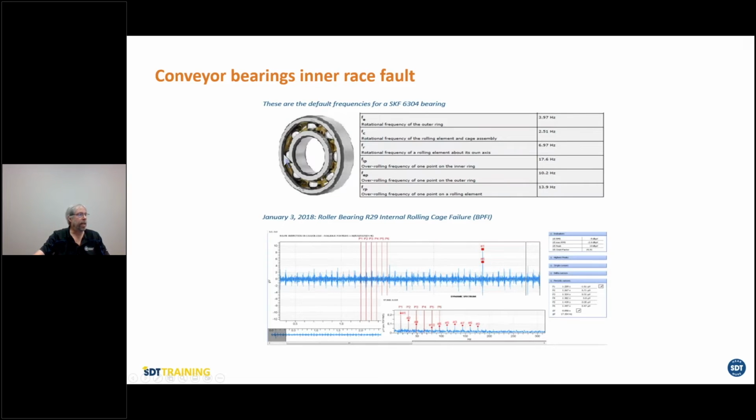Here is again another picture of a bearing where the outer race, inner race is all calculated for us. We just simply take this and multiply by 238, and it gave us the impact distance over here in the time waveform, and the spectrum right here, bang, bang, bang, bang, bang. We knew it was an outer race problem. So that's how we can determine the problem. If nothing was appearing here, there's no problem. If something's appearing, of course, there's a problem. It's not rocket science once you know how it works.